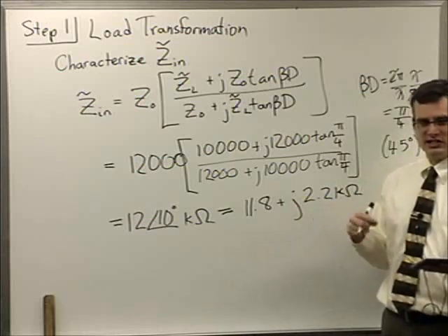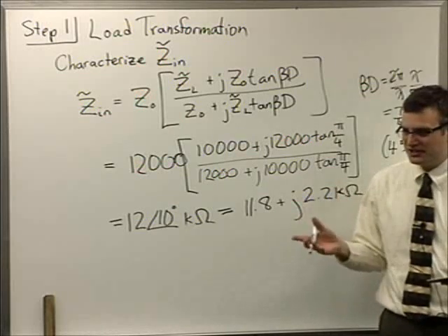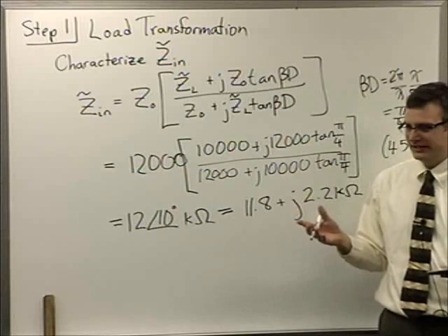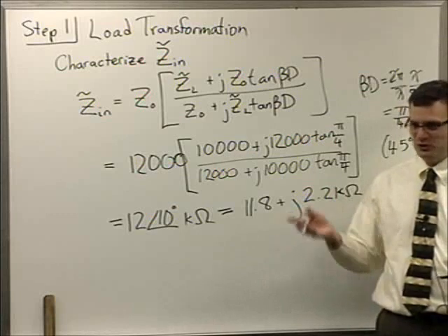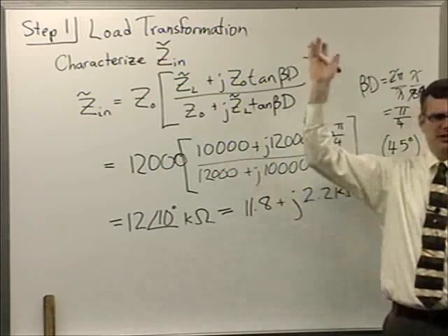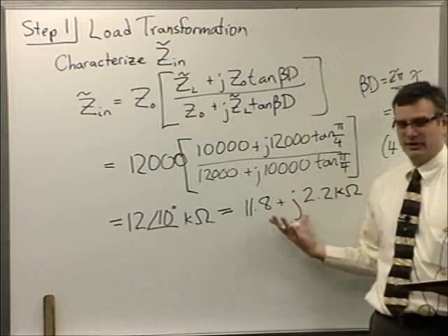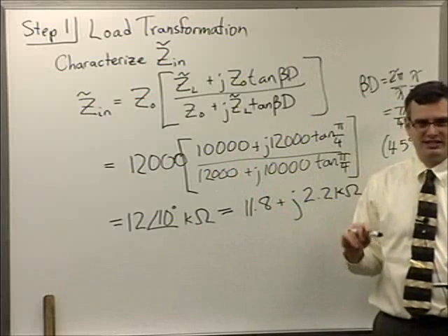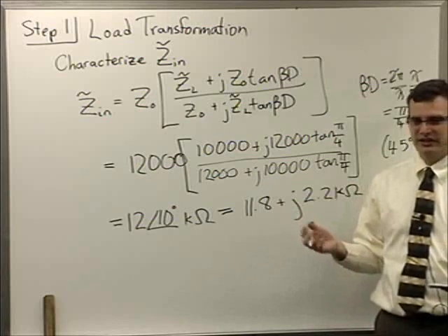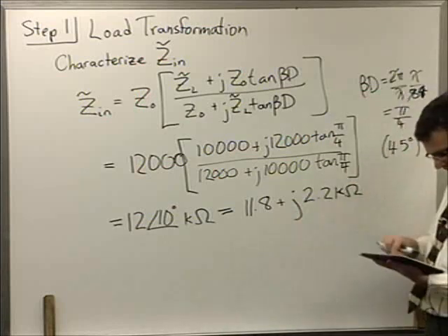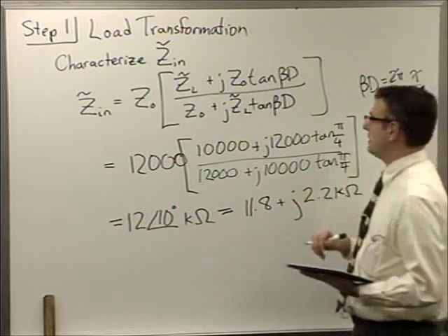The mismatch will cause a slight VSWR, which is important when you're transmitting hundreds of thousands of volts. Right? You don't have quite the same level of tolerance of deviation in that kind of network than you do on your printed circuit boards and things, where you can say, 10, 20% deviation from my expected value, not a problem. Well, here you're talking about 100 kilovolts. So power industry is much more sensitive to transmission line effects in the relative sense. Okay, so that's our first step.